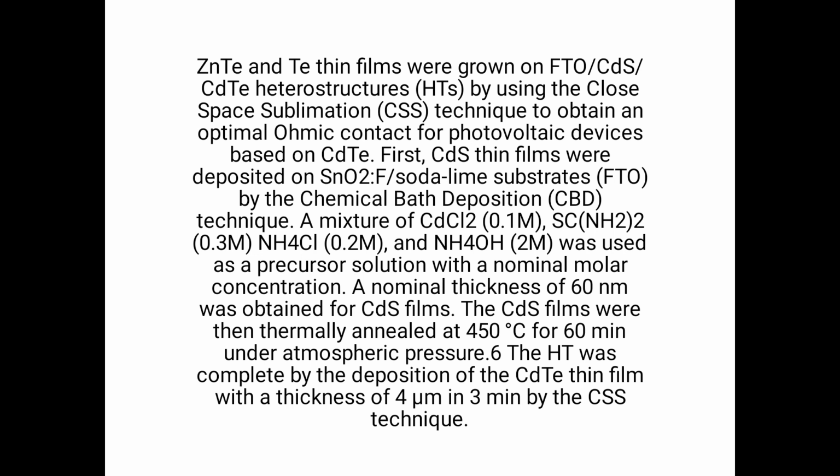ZnTe and Te thin films were grown on FTO, CdS, CdTe structures by using closed space sublimation. The full form of CSS is closed space sublimation, a technique to obtain an optimal ohmic contact for photovoltaic devices based on CdTe.